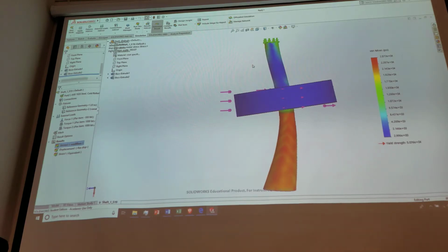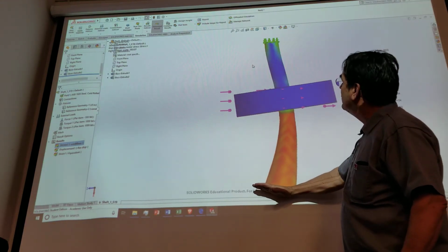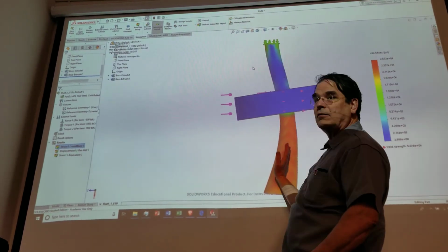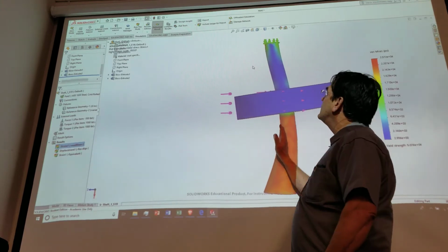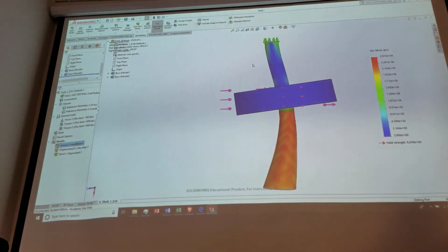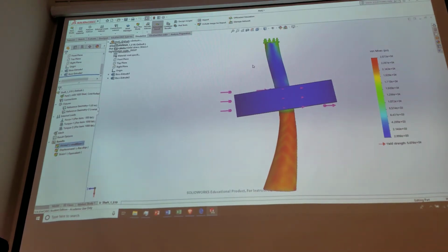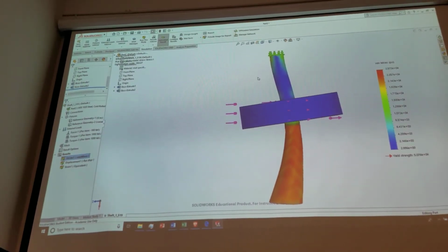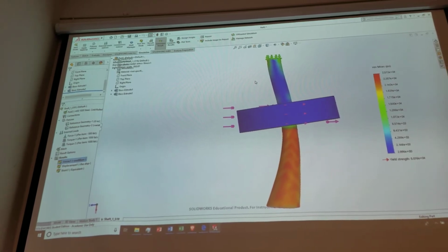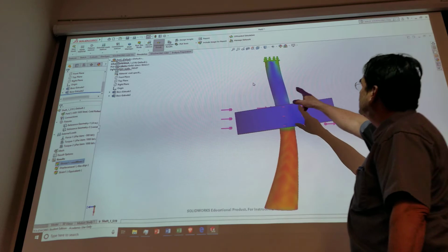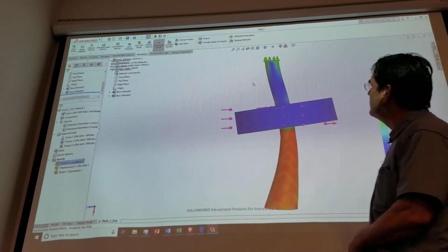And it also ought to be partially rotated, because when we push this way, this thing ought to make a bend. And what's it doing? Making a bend and it's snaking back. So what's happening? Well, that darn axial constraint is screwing things up. It's not letting it rotate in there, not letting it bend in there. So this axial constraint up there is screwing things up.